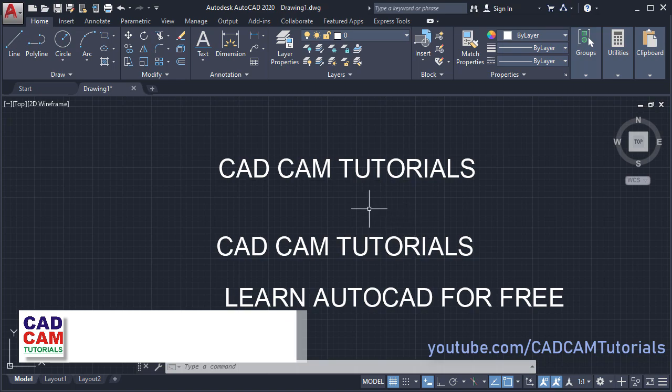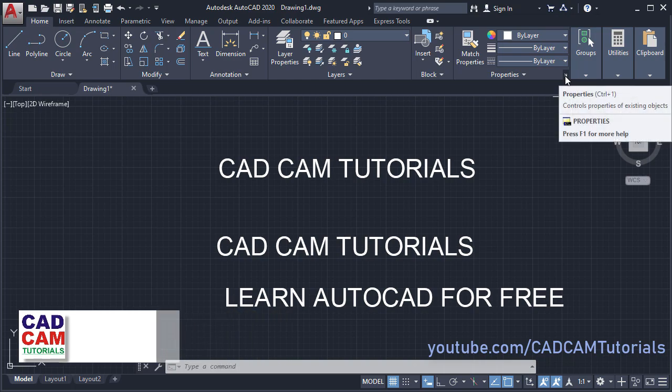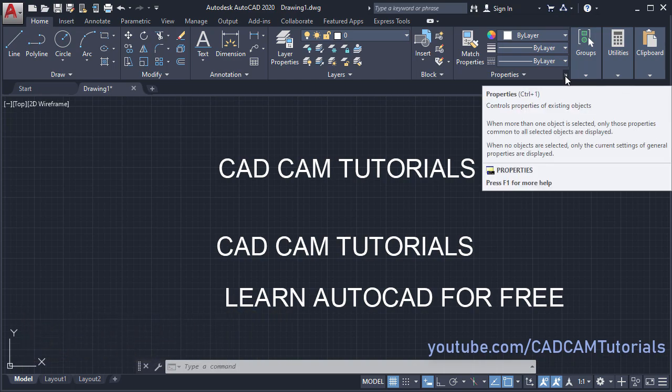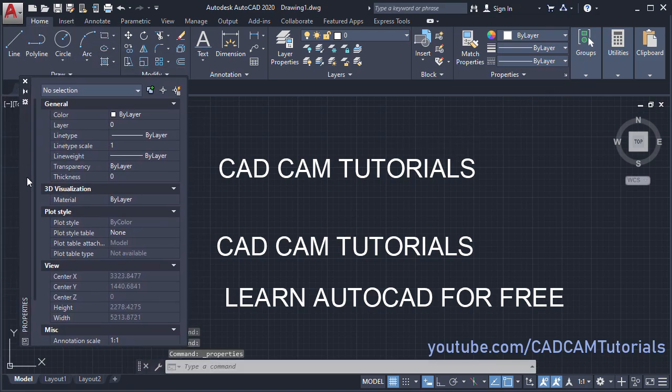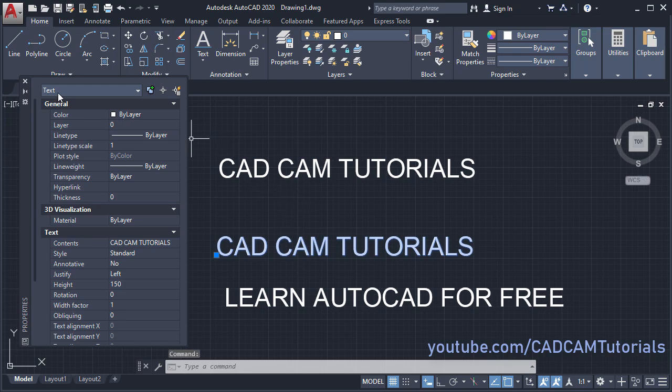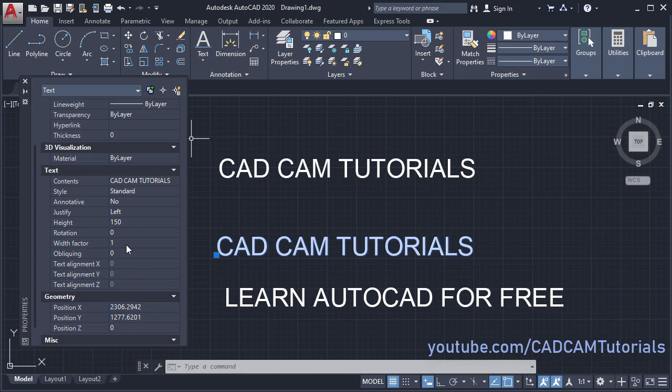Then if you want to change height or any other properties, for that you will have to use this properties command. If you can't find this properties command here, then the keyboard shortcut is PR enter. So click here on properties. It will show this properties window. Right now there is no selection, so you will have to select the object for which you want to change properties. So I will click here on this text. Here it is showing text has been selected, and from this text section you can make changes.